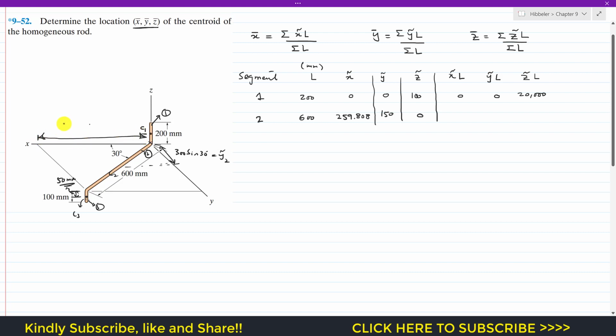So this is x tilde 3. This length is 600, and if this is perpendicular, then x tilde 3 will be 600 cos 30. Similarly, the y tilde of this C3 will be this much distance from here to here, and this is 600 sine 30 degrees. And as we can see, this C3 is at a distance of 50 mm in the downward direction, that is parallel to the z-axis.